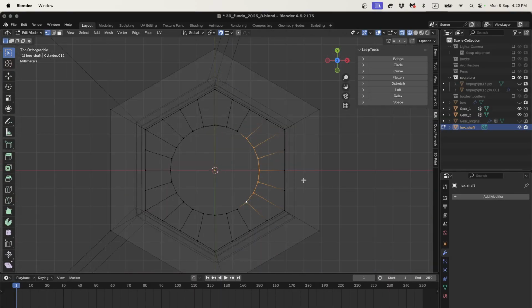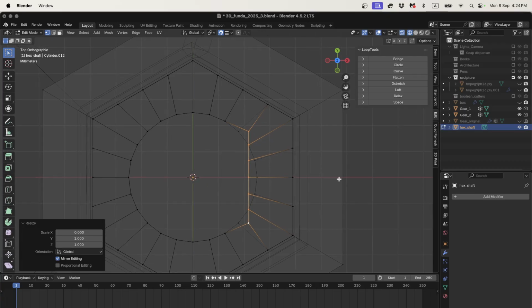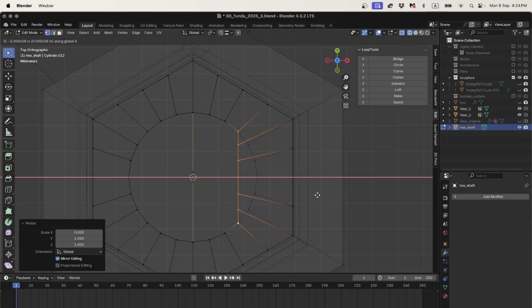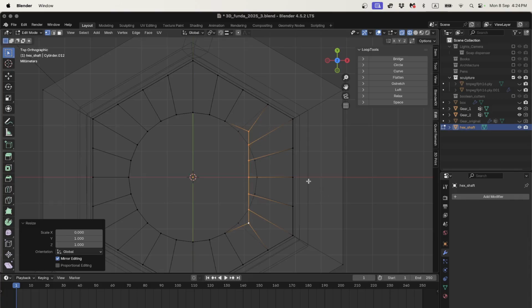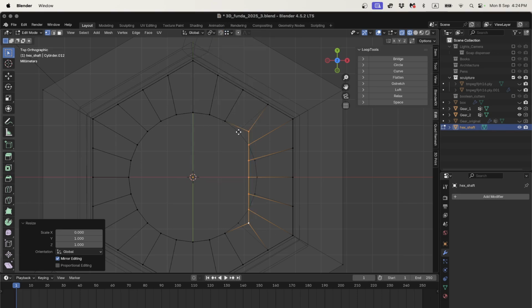And then with those 7 vertexes, I'm going to press SX0, which means I'm going to scale them all on the x-axis by 0, SX0. So now they're flat. Okay, so that's one part of it done. Then I'm just going to turn my snapping off for a second. I'm going to press G and X, and I'm going to bring them back up to be in line with the circle. So I can actually use my vertex snapping here, and I can just press GX. Oh, have to turn it on. GX, and there, I've got that snapped up. So now I've got a 5 millimeter D shaft.